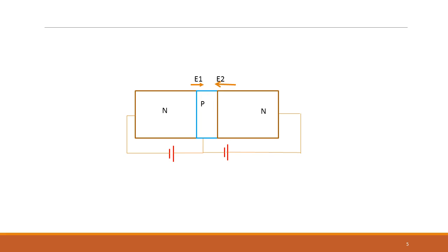Here, instead of a hole current, an electron current will flow from the emitter through the base, and instead of being collected at the base, it will get swept across the base-collector junction. Remember, this width is so narrow that it hardly finds time to recombine. The field which is present here just sweeps it across. Right? So instead of the hole current, you see that's an electron current.